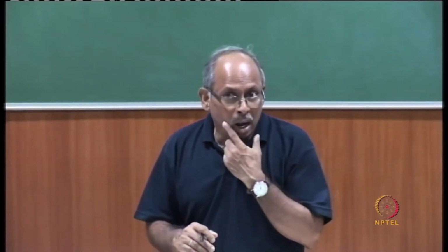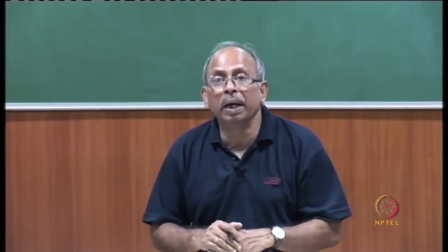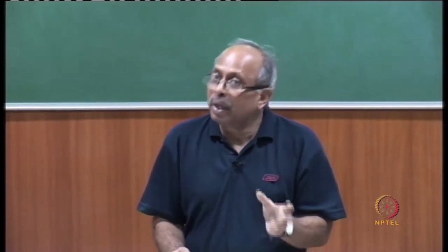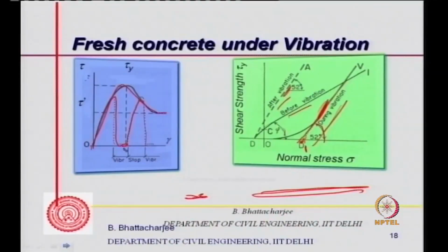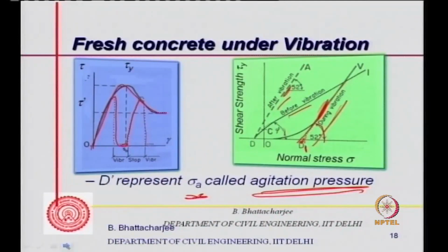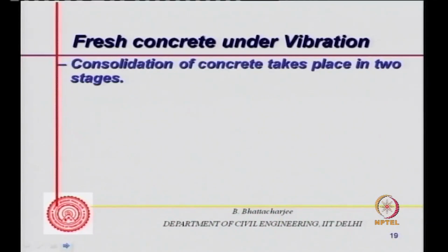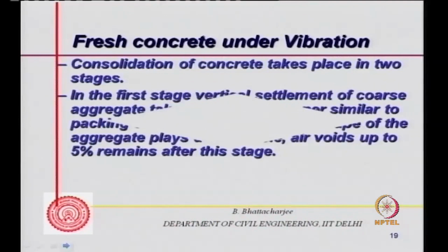Shear flow would be occurring actually, and then due to this, the air will be driven out, and it can get the right kind of shape of the mold itself. So that's the mechanism of vibration. Fresh concrete consolidation actually occurs in two phases.